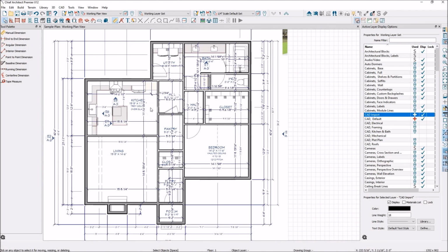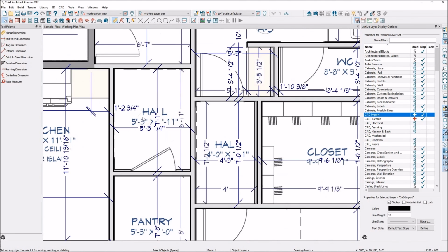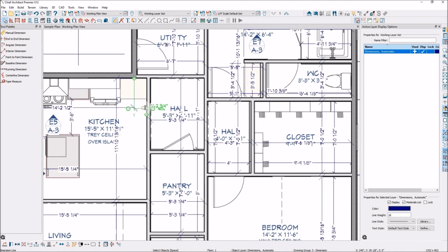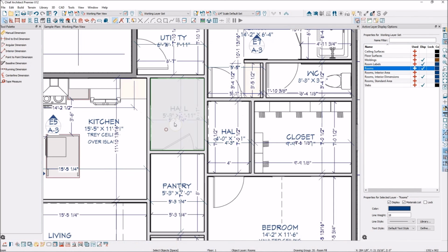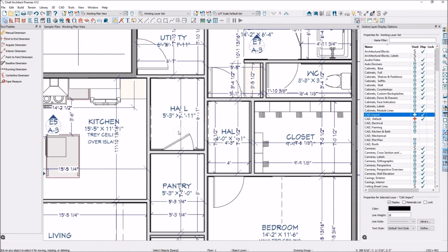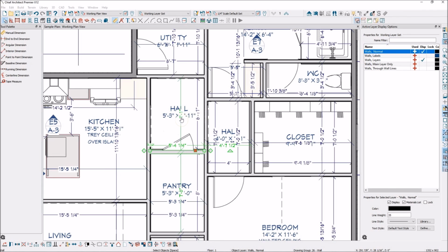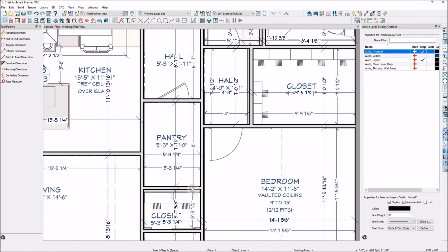And some of these rooms I'm not going to be using interior dimensions because we used this framing dimensions here. So those don't show on the other plan, but I can leave those there to just show. But on these interior walls here, we are going to use them. But I'm going to just go in and clean some of this up because it does get kind of messy. So I know this wall isn't moving because it's connected here and I want that to line up. So I'm going to move this wall and let's see. I'm just going to move this to get rid of that dimension. So it should be 6'11" there. So 6'11", and that should be 8 feet.